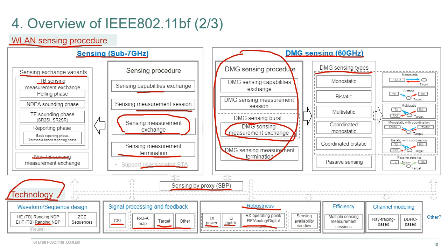It's very important. I can give you a simple example. When you receive the channel 2 times, you find the channel changes, right? If we do not have such a requirement, you cannot identify whether these changes are caused by environment changes or by receiver AGC changes, right? If we can further provide some information about the AGC level, then you can identify where the change is from. Right?